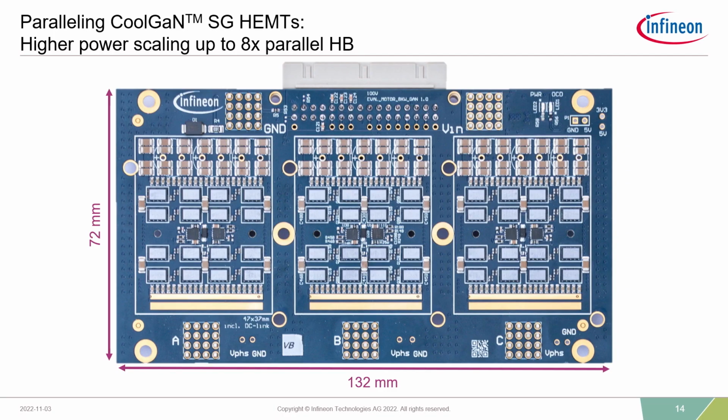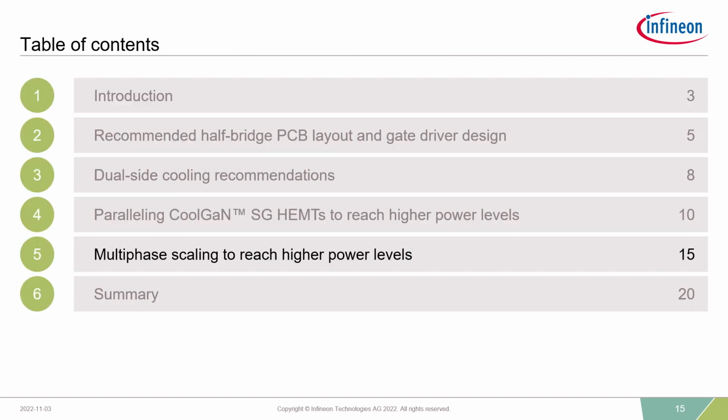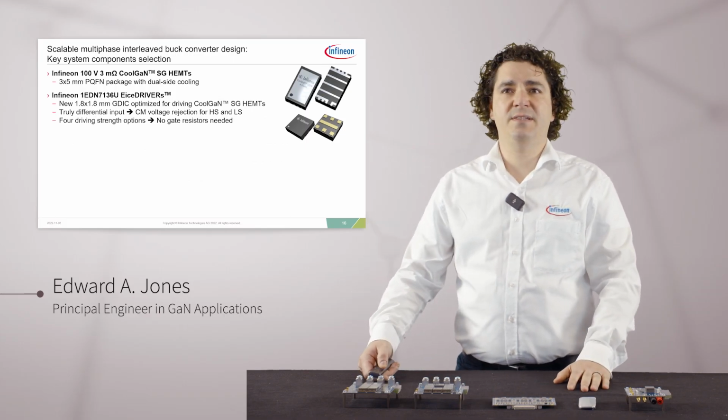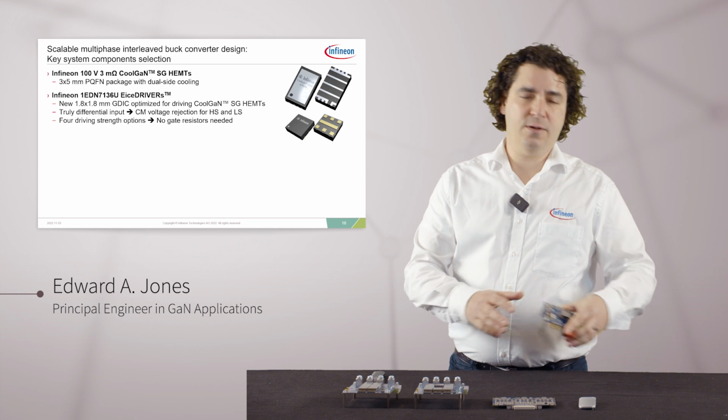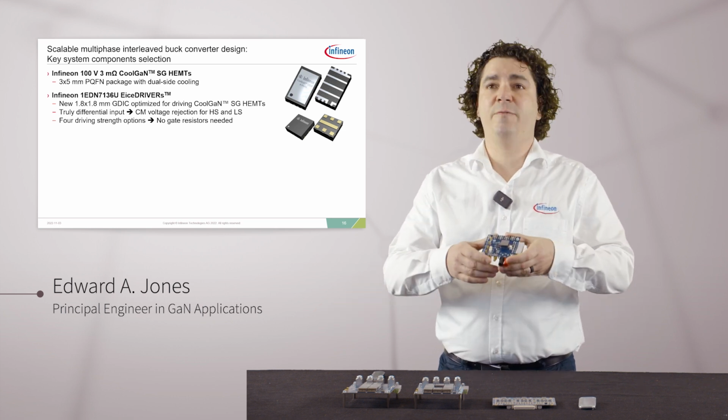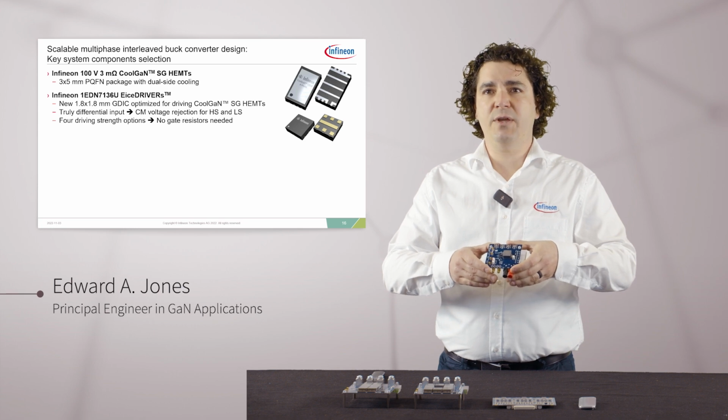Here we've just discussed motor drives, and in that case paralleling devices makes the most sense. But what about DC-DC converters? In this case, maybe not. So if we look at a single DC-DC converter stage, like here we have a single phase buck converter, it is the basis of all of these designs, this single half bridge and a standard half bridge evaluation board.